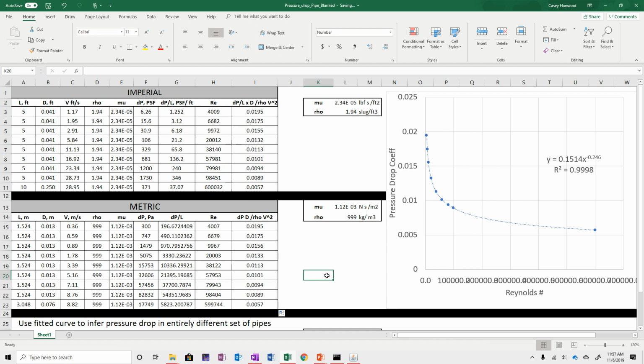the dimensionless variables here, the Reynolds number and the dimensionless pressure drop, are the same within round-off error if we compute them with metric quantities as they are with empirical quantities. This shouldn't be a surprise because, like I said, they're dimensionless, they're independent of the system of units you use. There are some small differences here. Like I said, those just come from the round-off errors and the conversions that are being used. But the idea is we've got our Reynolds number, our pi 2, and we've got our dimensionless pressure drop, which is our pi 1 term.